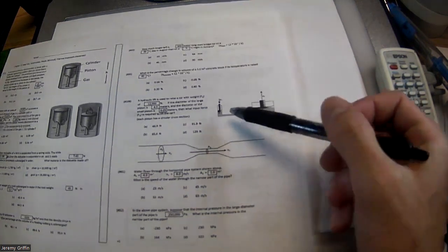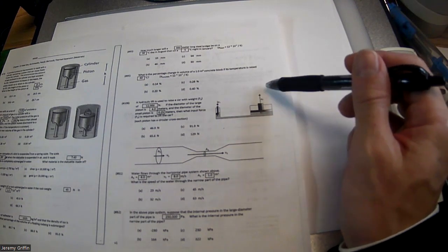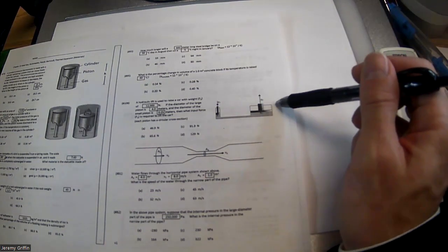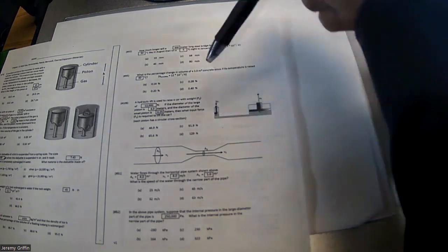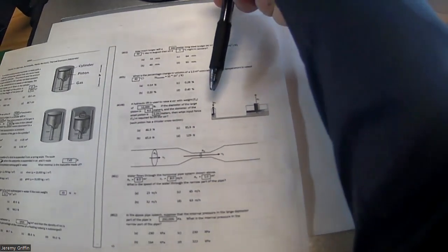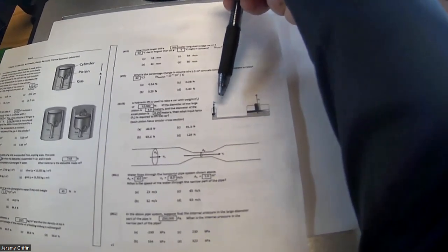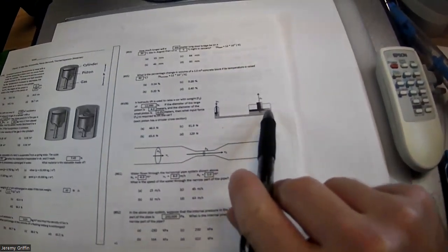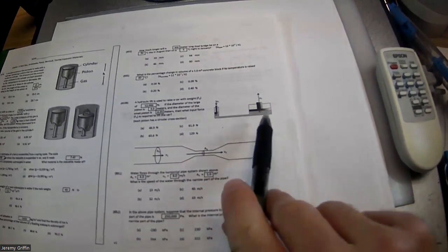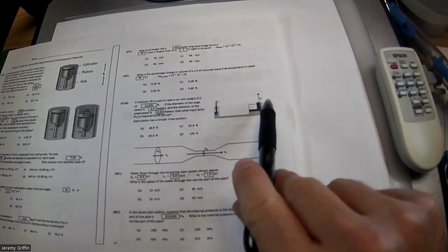And I think there's a similar thing here, because the hydraulic lift that I showed you guys in the presentation the other day had a vehicle over here, a whole car that was being lifted. So if you want to lift something very heavy with a small input force, I could push down with a small input force. Isn't that going to displace some volume of water, some tiny cross-sectional area times the height change? And on the other side, that would be an equal volume of fluid displaced over here, but divided by a huge cross-sectional area, it would only move up a little bit.